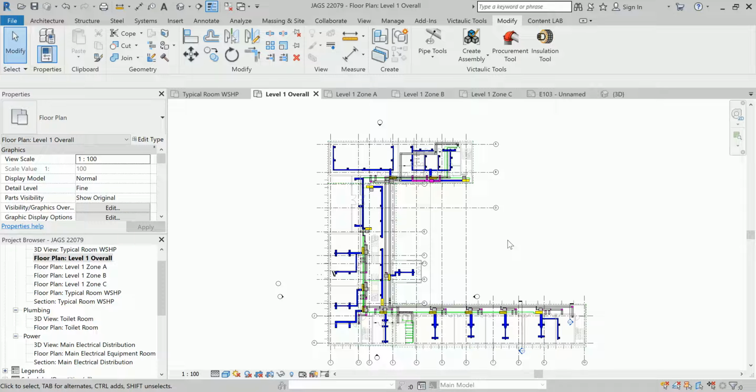Or what I prefer, and which is more effective in my understanding of Revit, is to export your overall master plan into a CAD drawing and then import that into an annotation family. I will show you why.